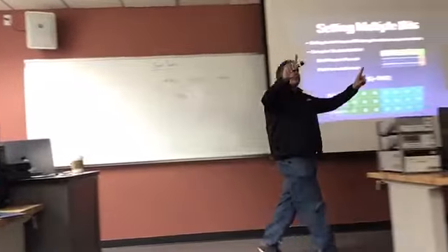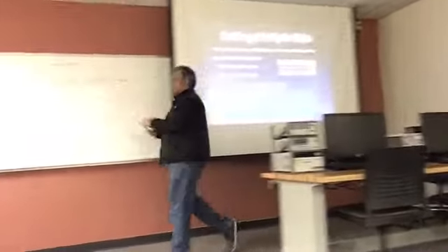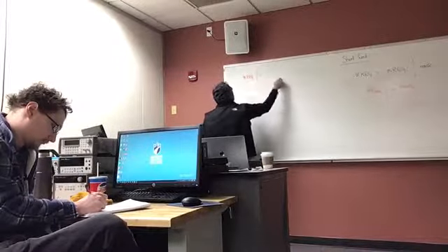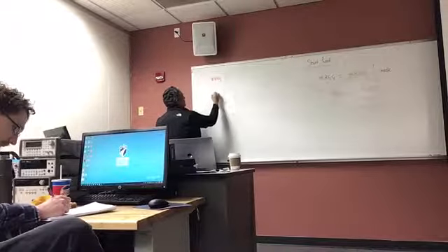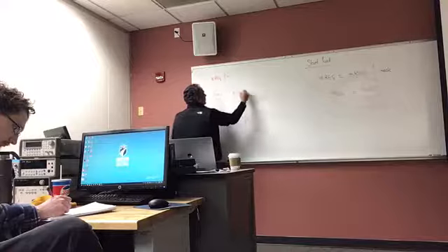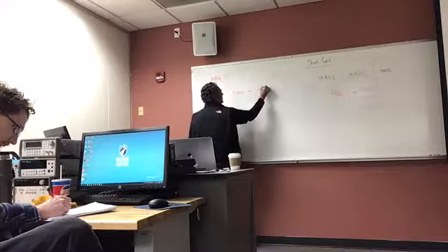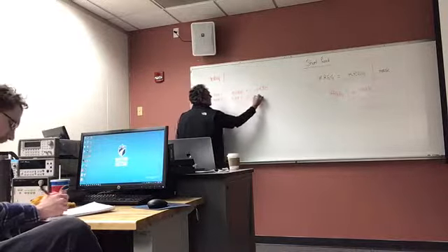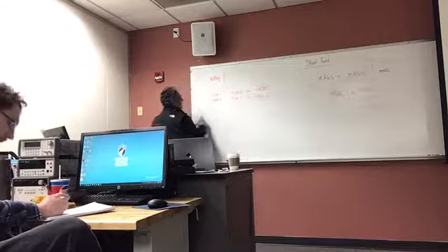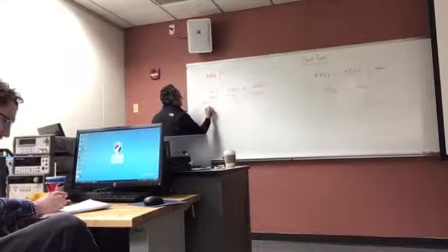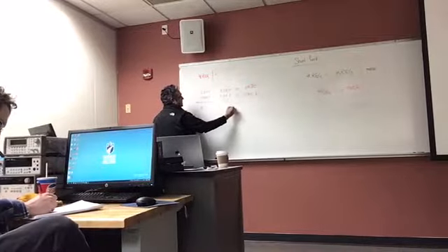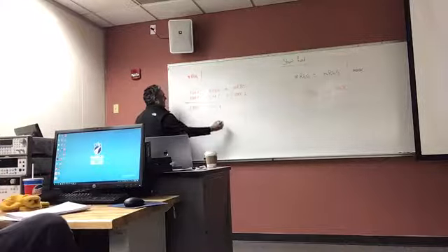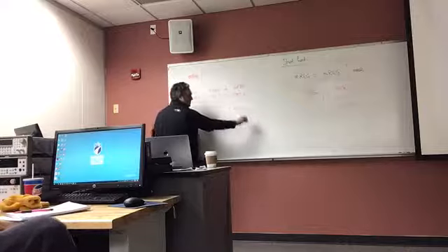Right? We have 2 circuits inside of one register. I want to set both of them. So you go, I have reg or equals, I need a number, right? And so bit 7 is this. According to that table, that's hexadecimal 80. And bit 0 is this. That's hexadecimal 1. Right? So I need this bit, and I need that bit. And this is hexadecimal 81.